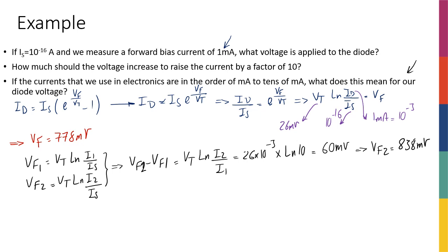So you can think about it, if you have a conductor with a width of a few, like 1 or 2 micrometers, and you have a huge amount of current, and by huge I mean hundreds of milliamps flowing through it, that conductor is going to just burn, right? It's going to get heated up and it's just going to damage everything, right? So generally with microelectronics, we are really talking about at most milliamps and tens of milliamps. We're not going to talk about anything higher than that. Generally low power electronics with, like, for example, implantable devices and things like that, we're really talking about microamps, and in some certain blocks, we're really talking about nanoamps and picoamps and even femtoamps, right? So here we're talking about like milliamps.